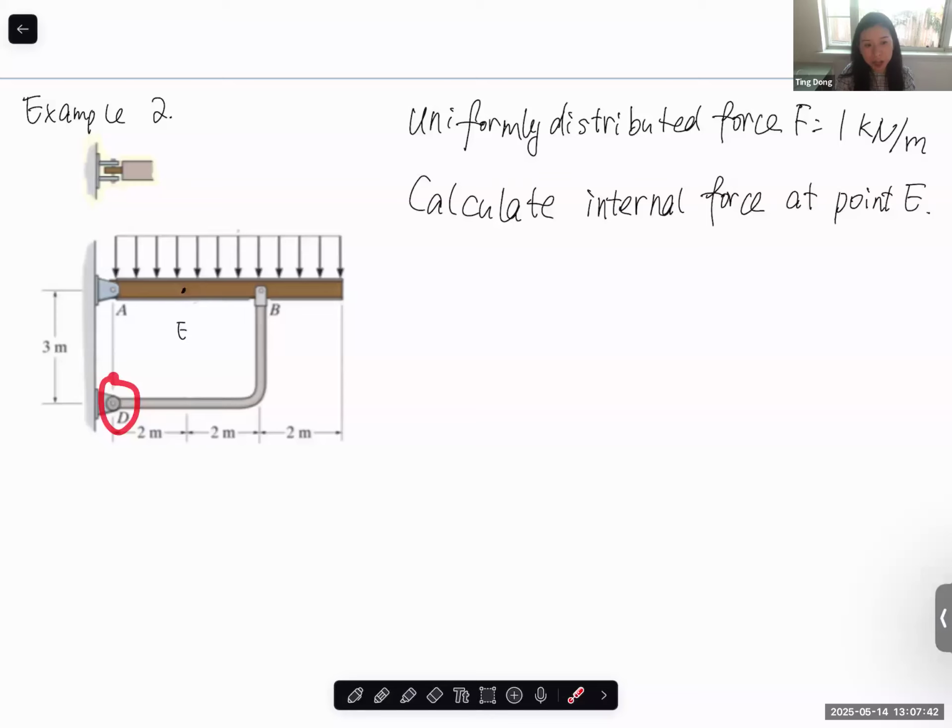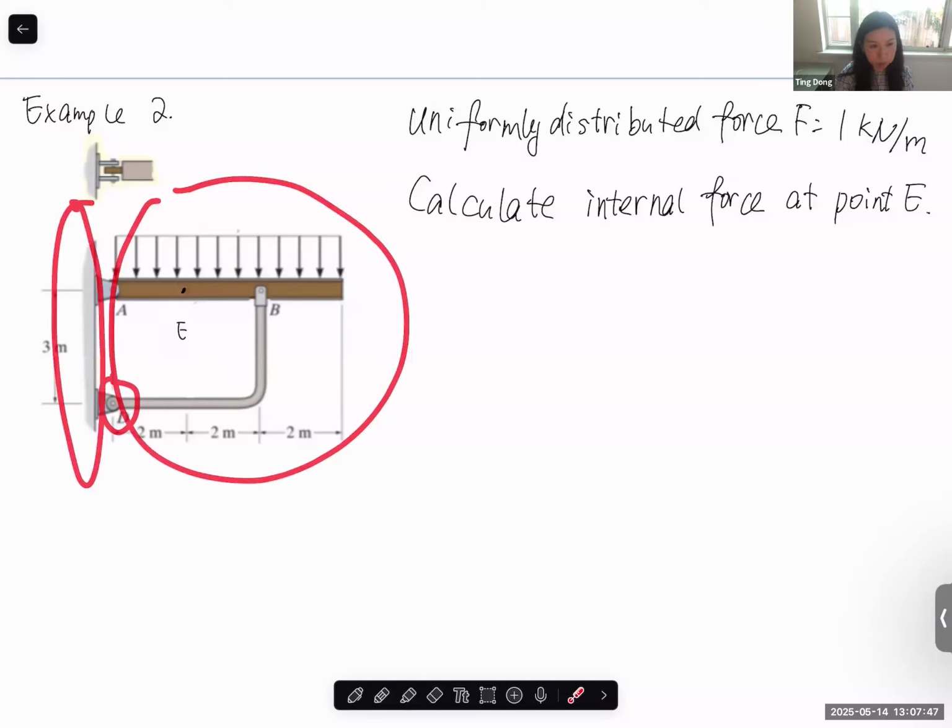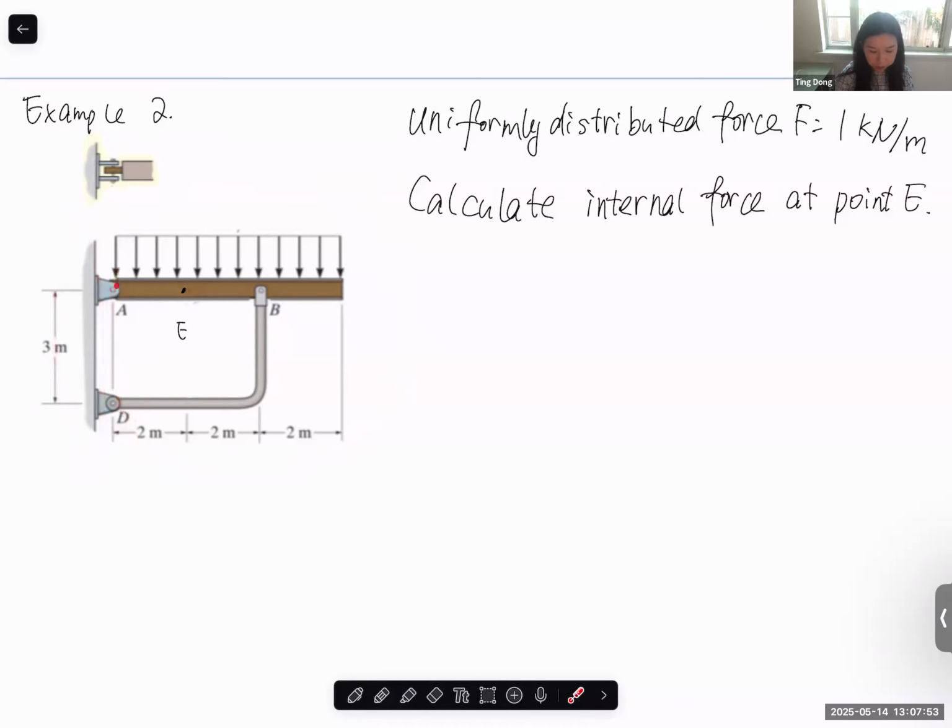So now for calculating the reaction force, let's separate the whole structure from the wall. Now we have three unknowns and three equations. This one is a straight member, but it's not a two force member because it has transverse force, force applied at B and the reaction force here. So this one is truly AX, AY, two independent unknowns. But here at D, since DB is a two force member, it becomes one unknown.